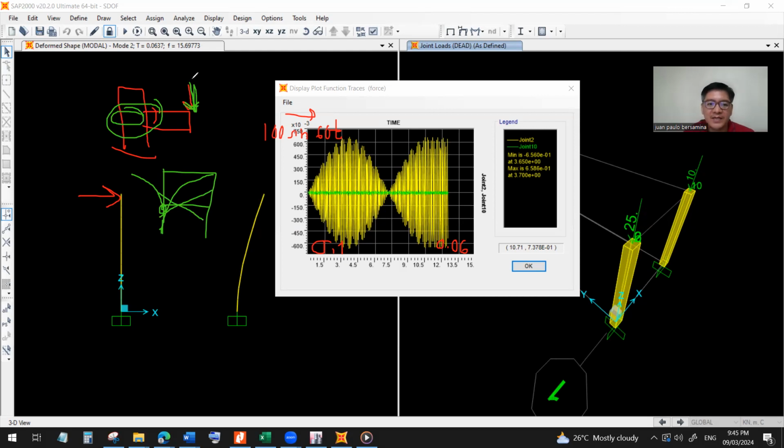So by applying load here, you're applying a moment at the joint, which is maximum. So you simulate the response of the joint in an actual earthquake. By getting its response, for example a force deformation curve, you know its capacity, and that capacity will be needed in nonlinear analysis. So that's it for the undamped force vibration.